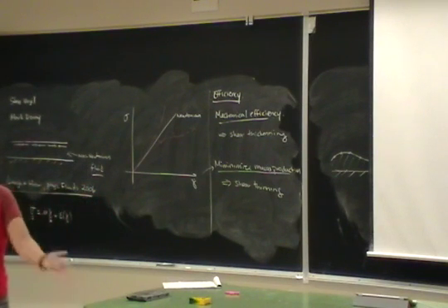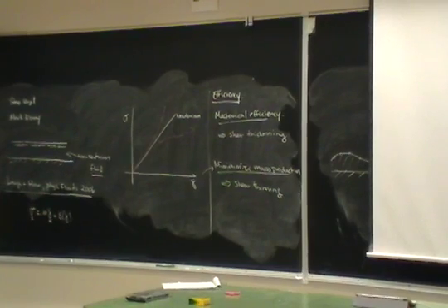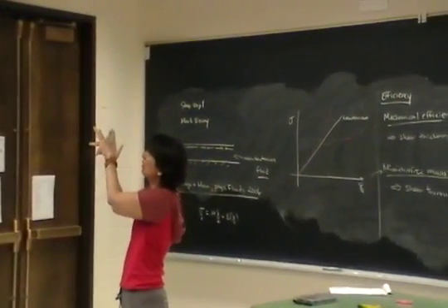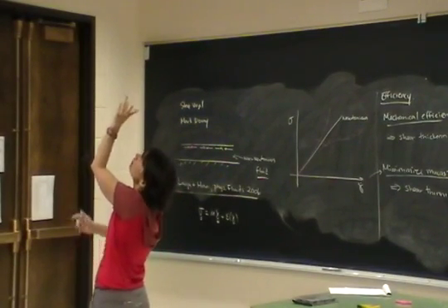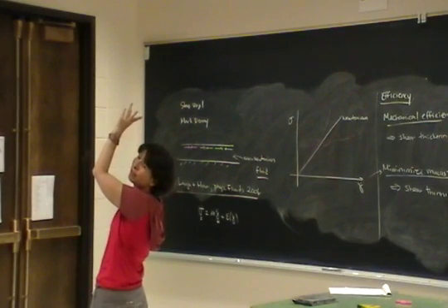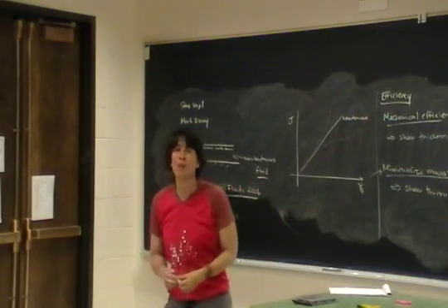With snails, you don't have to worry about balance, timing, or torque coming off the wall, because you just glue to it. So we have a couple of snail bots. And this is also an interesting question: it turns out it's easier to climb upside down across the ceiling than to climb walls. If you're climbing a wall, gravity is both trying to pull you off the wall because of the torque, and impeding your progress. But if you're on the ceiling, gravity is only acting to pull you off, not impeding your progress. So the robots actually go much faster climbing inverted across ceilings. I don't know about real snails. We haven't raced them up.